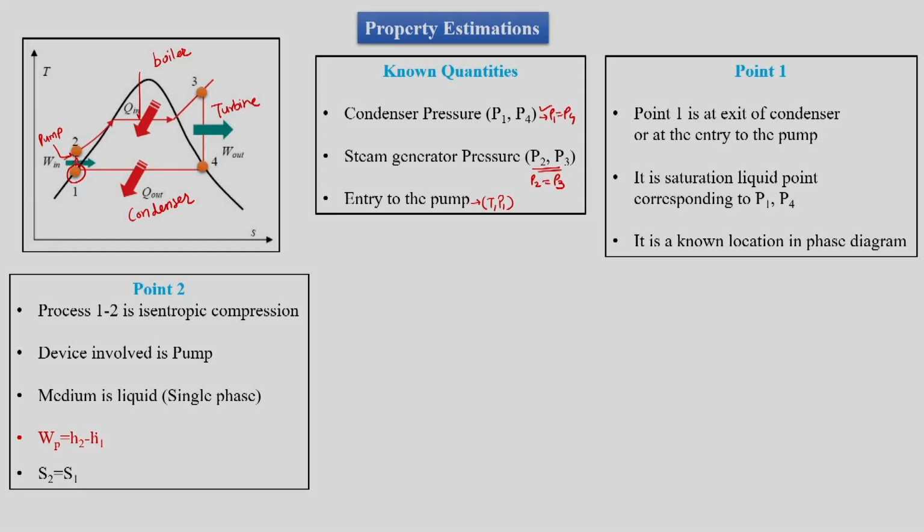We should remember the formula or the method of interaction of heat and work that we discussed for the open cycle, where we used the steady flow energy equation, where we said that Q minus W is equal to the summation of energies like enthalpy, kinetic energy and potential energy at all the inlets, minus the summation of energies like enthalpy, kinetic energy and potential energy at the outlet.